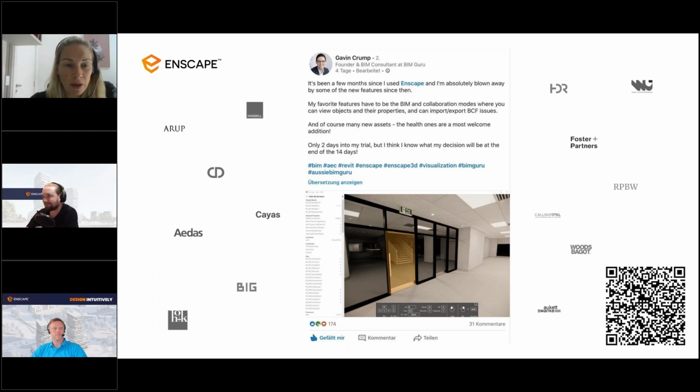Kai, you were talking about creating a video in Enscape earlier on. Someone here has asked about video speed and whether it's possible to keep the video speed universal throughout. They're saying, if I change one camera's speed, do all the other cameras' timings get adjusted? If you change one camera speed, to recap, that is the timestamp value per camera, Enscape will actually maintain an equal speed throughout the video. If you change two, or if you key two, it will change throughout the video. So if you want to have an equal speed throughout the video, I would recommend to keep your hands off of the timestamp